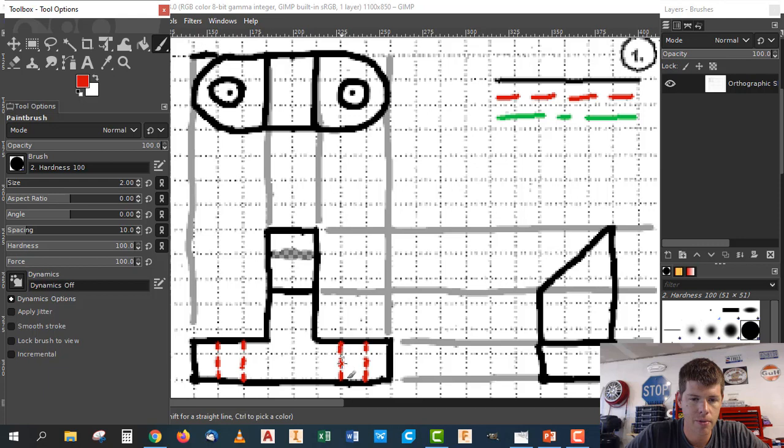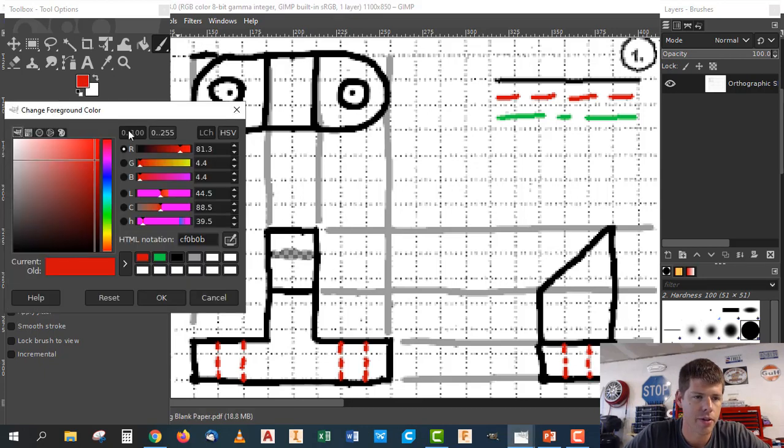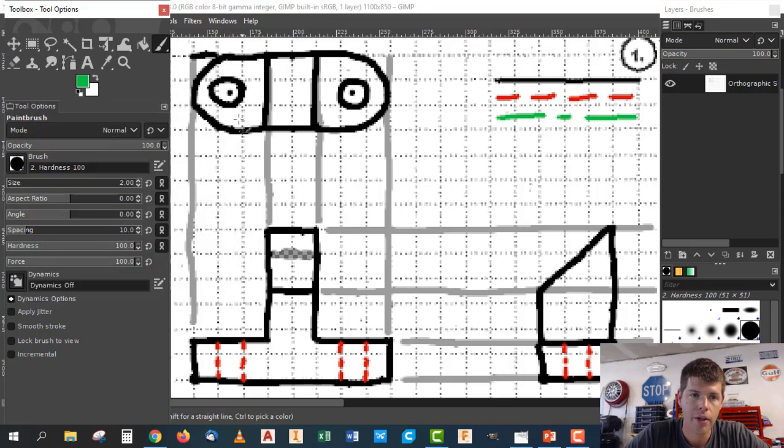So now we got the visible lines here. Let's go ahead and or sorry, we got the hidden lines here. Let's go over and do the hidden lines here. We know that same hole is going to go through the edge of this part on the right side. And then very last, we just have to put in the center lines. So anywhere we have a hole, we're going to do a center mark. The center mark looks like this. That goes in the hole, and then corresponding to that on the side, you have a center line. Okay, so I'm going to try my best to draw these things in.